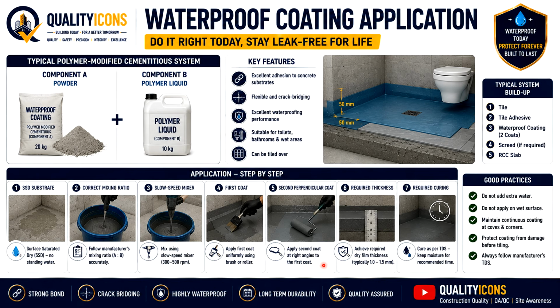Apply the second coat at right angles to the first coat. Required application rate, thickness and curing period must always be checked against the approved product technical data sheets or your methodology. And one important site warning: never add extra water just to make the coating easier to apply. Changing the designed mix can affect performance. Finally, check the required thickness and required curing.